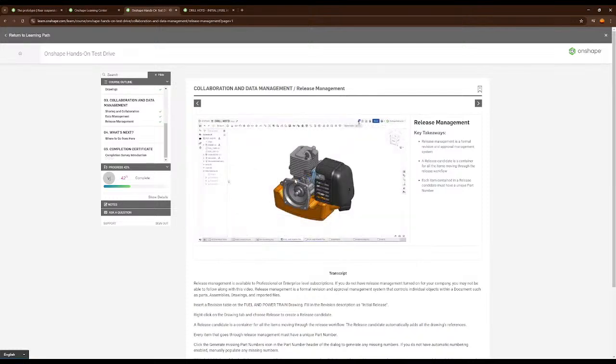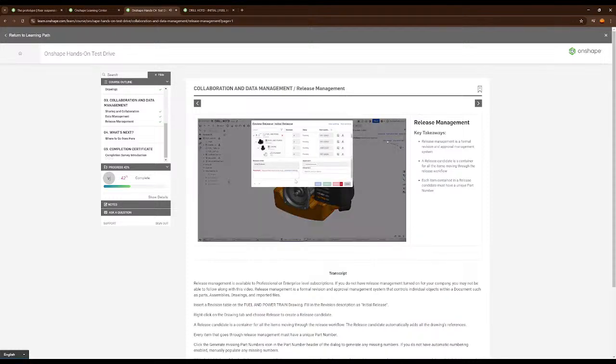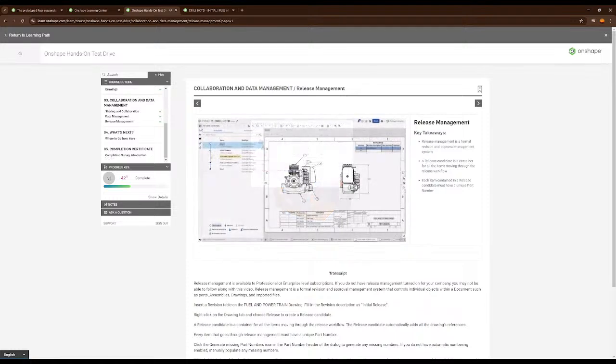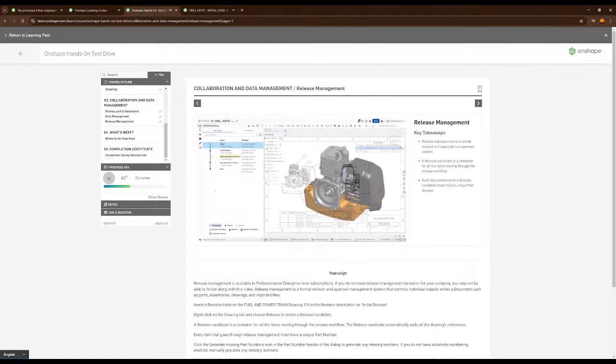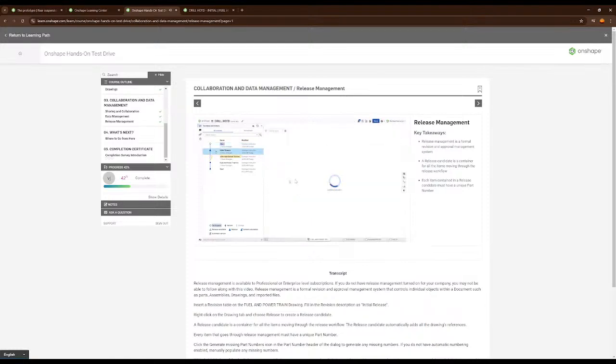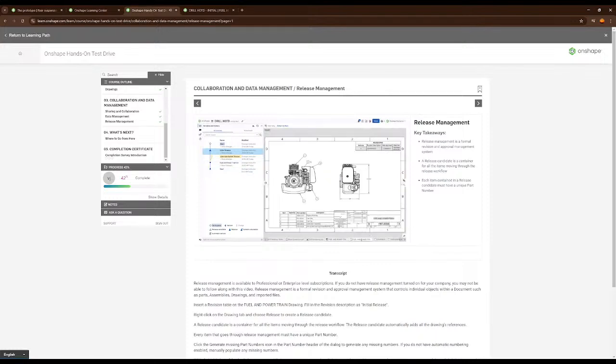If you submit the release candidate to an approver, they will receive an in-app notification and an email. The Versions and History panel shows the outline of a triangle for the appropriate version, indicating it has not yet been approved. Once it is approved, the released version shows in the Versions and History panel as a solid triangle. If you open the released version, the drawing is updated with the approver's name and approved date. If you released it yourself, your name is entered as the approver.